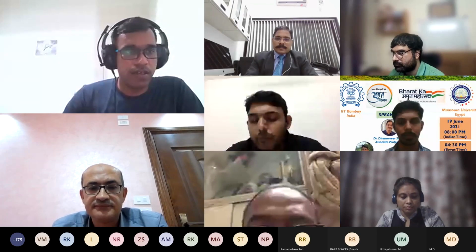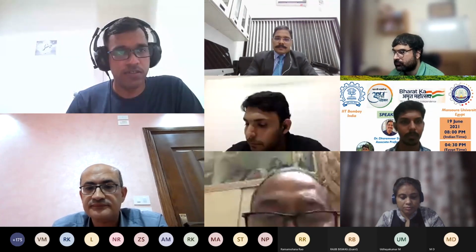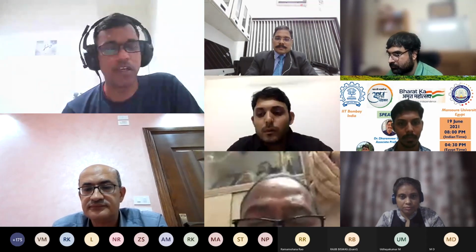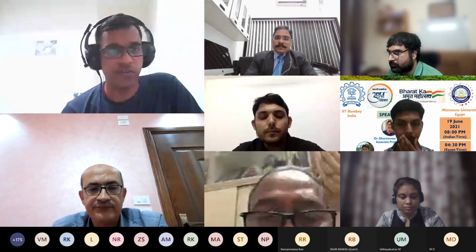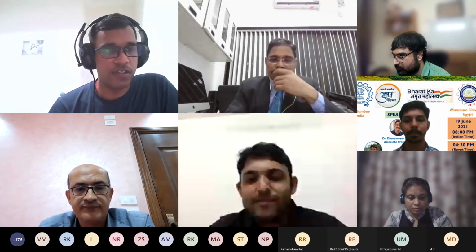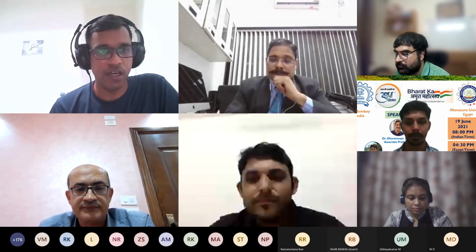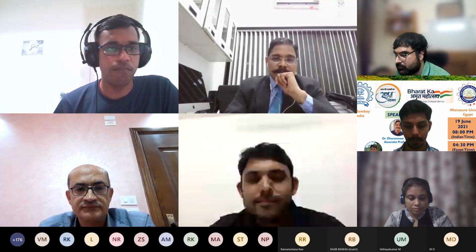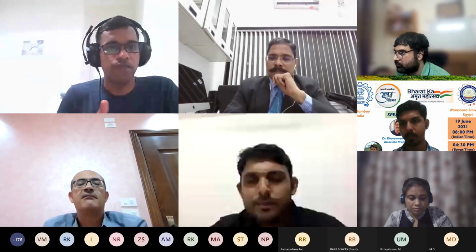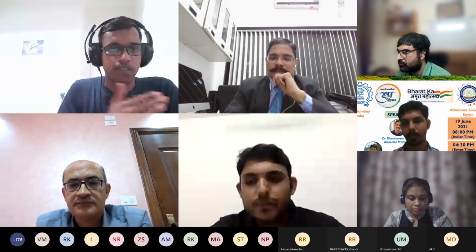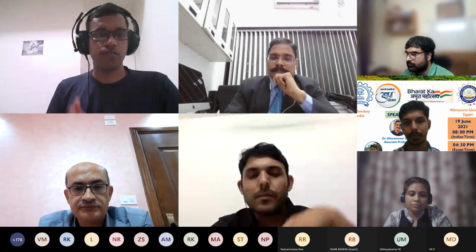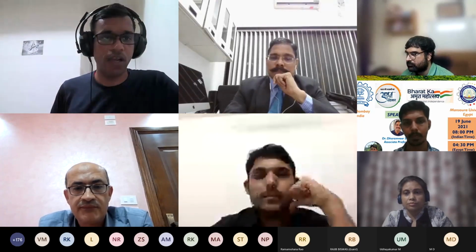So another interesting question has come up on the overlap for VG30 and VG40 grade. I think this question was asked by Mr. Deepak. So essentially, as you rightly mentioned, there is overlap. For VG40, if you take 20% plus and minus, and for VG30 20% plus and minus, some overlap will be there.